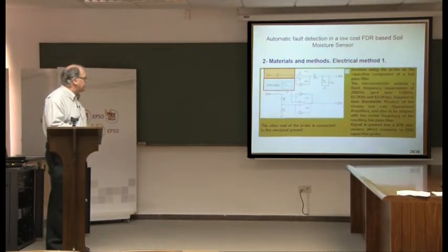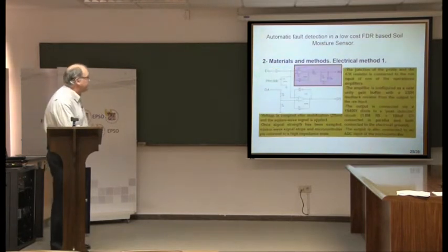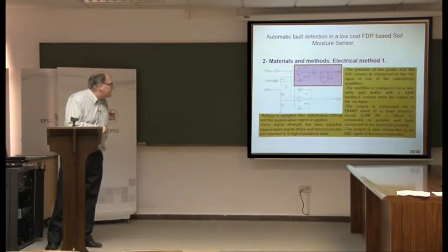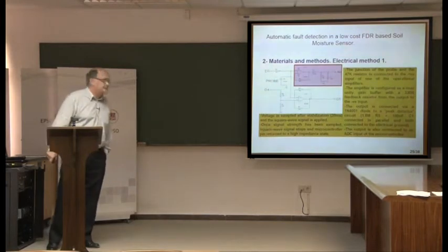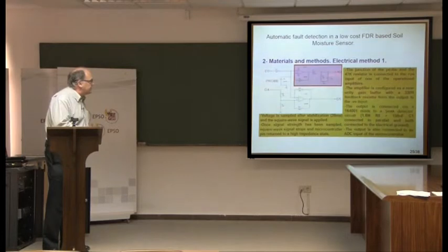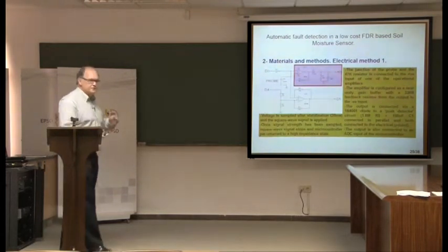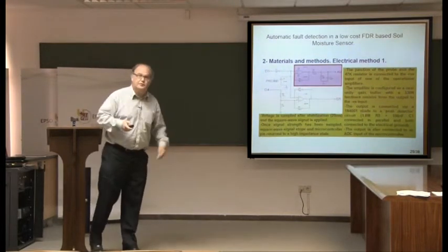Basically this is then passed on to a unity gain amplifier stage to impedance match these two components. We then pass this on to a peak detection circuit so that the analog voltage that's read here gives you some idea of how much was reflected by the filter system. The values here are recorded using a 10-bit analog to digital converter, but we then rescale those to between 0 and 255 for ease of storage and transmission.